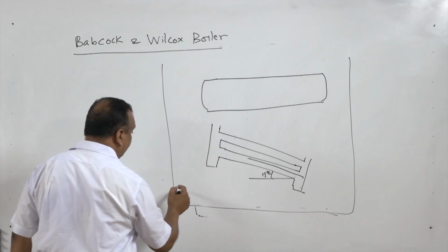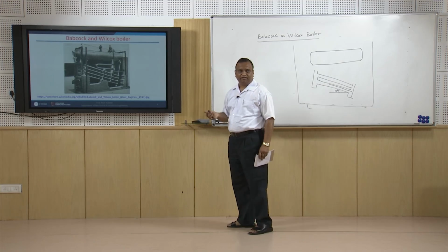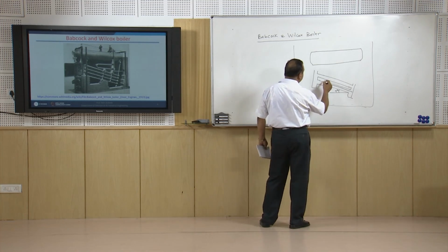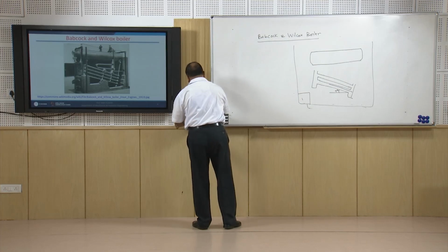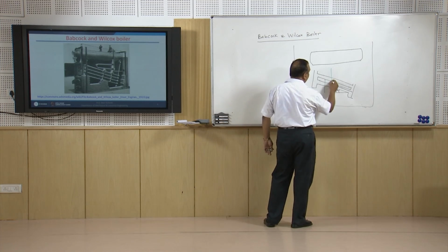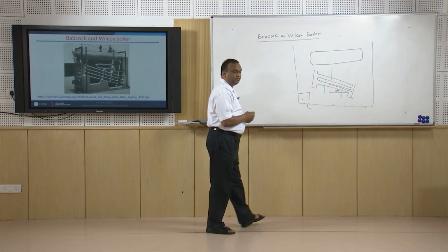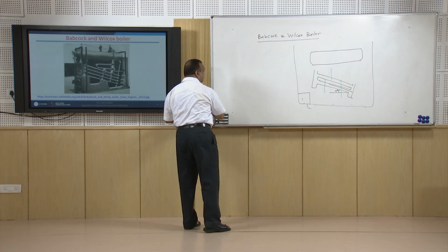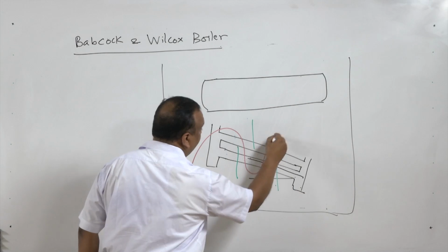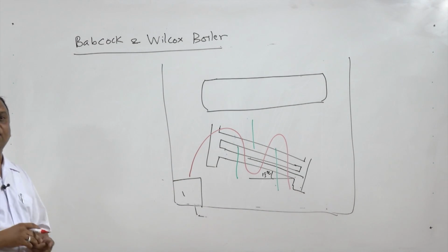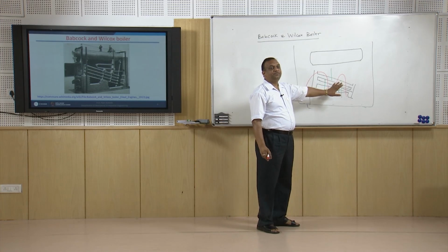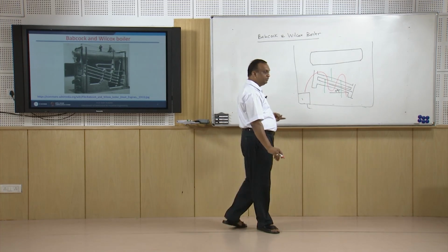This boiler has a grate. Most of the arrangement is the same. It has a grate, right? The fuel is burned inside, and then there are baffles here also. In this boiler also, there is a provision of baffles. The purpose of providing baffles is that when the flue gases move over the tubes, they move in a zigzag way, and they cover the maximum path. When they cover the maximum path, the heat transmission is maximum, so the efficiency of the boiler is improved.